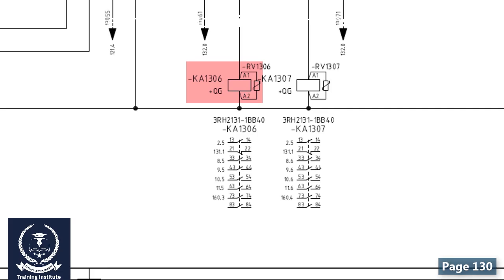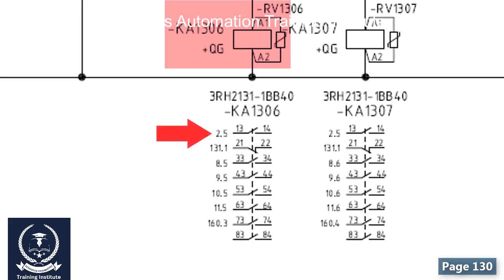If you have seen the legend and abbreviation page of the drawing, you know that the KA is a nomenclature for a relay in this drawing. Below the coil, you see the 1314 contact of page 2 and also the other NO and NC contacts of this relay, with the addresses they have been used in this drawing. We'll come back to this page very soon.